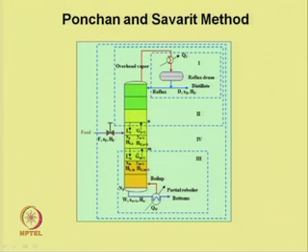Section 1 incorporates the reflux drum, distillate and the reflux, and the condenser over here. Section 2 is above the feed plate, which is the rectifying section, and then section 3 is below the feed plate, that is the stripping section, and then we have the overall column balance, which is section 4.